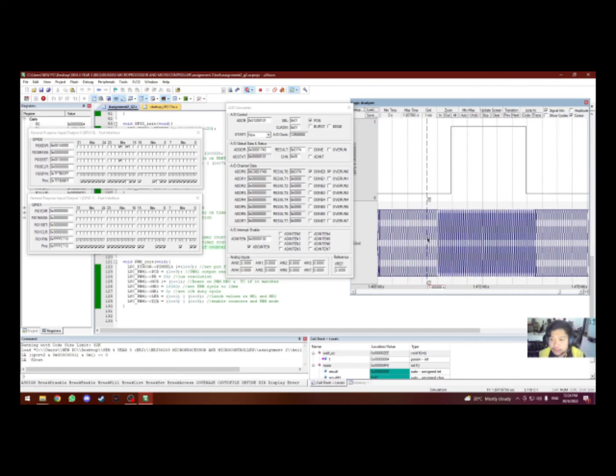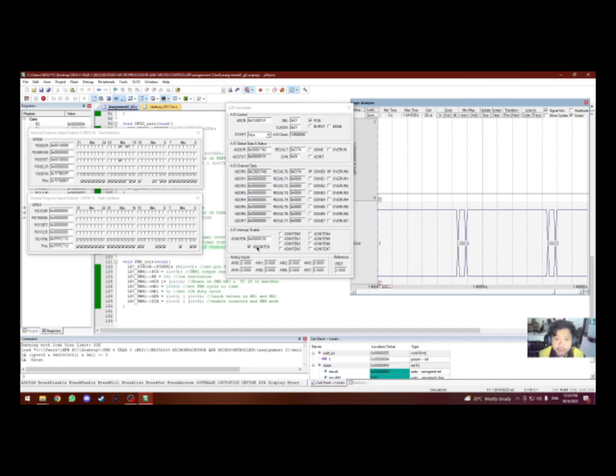After we run it, we get P18 as 0, which is off, and P20 is on. This means the temperature is too low, so we need to raise the temperature higher, between 50 and 70 degrees Celsius.